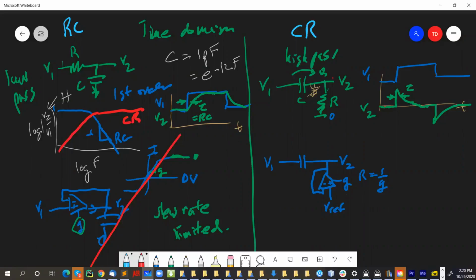Because these basic ideas should be self-evident to you without all the fancy mathematics. And now we're just going to do the math and consider the large signal responses. Just to be clear, when V1 is high on the high pass filter, even though it's high, no voltage is being passed to V2, right? Because the capacitor is just like saying, no, I'm not passing that frequency, which is 0. Yeah, the capacitor just blocks any DC current from flowing.